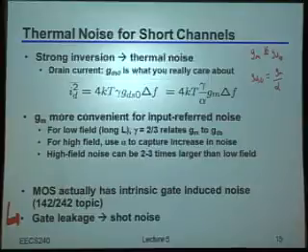And by the way, just in case you're thinking I'm just mentioning this and it doesn't matter at all, user beware, because particularly in some of the not latest and greatest technologies, but maybe a generation or two back, 90 nanometers was actually about the worst for this. It turned out that if you looked at a MOS transistor at the maximum supply voltage, and you closed your eyes, treated it as a black box, and looked at gate current and drain current, the so-called equivalent beta you would get, meaning the ratio of the drain current to the gate current, was only about 3,000 or so.